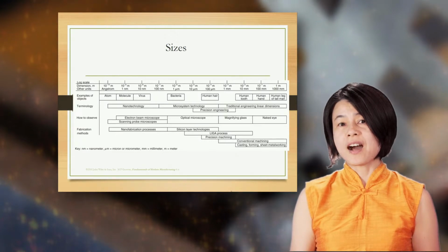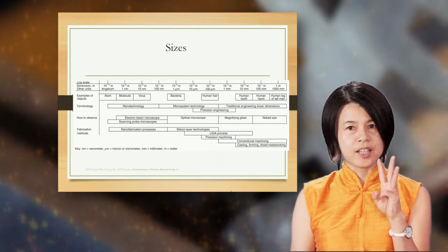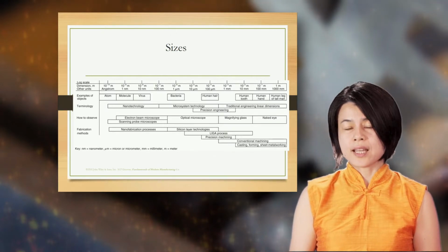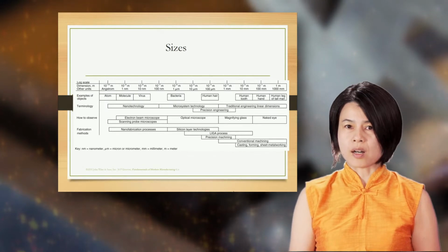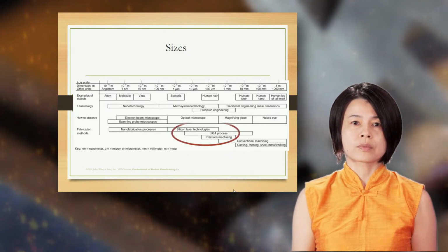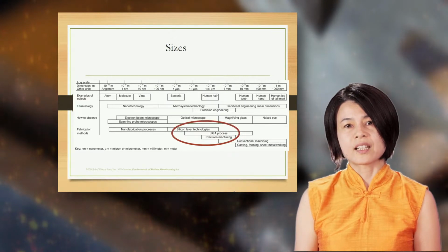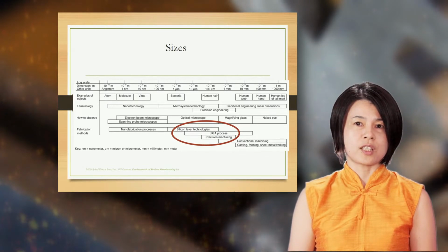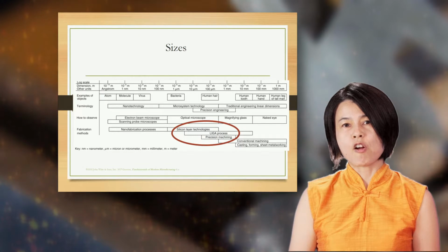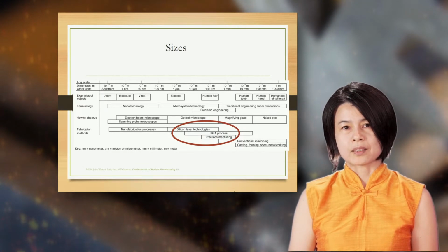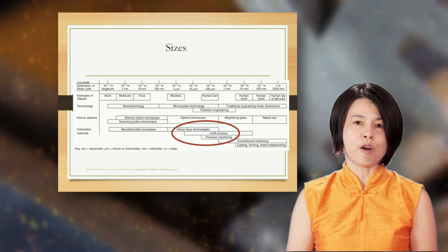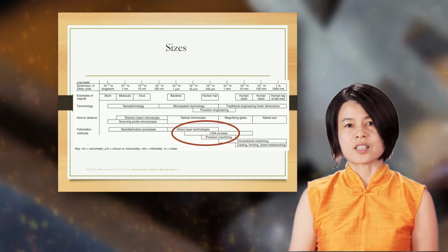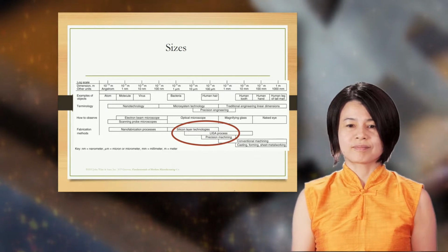Okay, have you figured out the answers? There are 3 fabrication methods over here dealing with microfabrication. When you look at the scale between 1 to 100 microns or micrometers, you will find silicon layer technologies, LIGA process, and precision machining. They all belong to microfabrication technology. But for this introduction level course, we will only focus on the one which is most well known, silicon layer technologies.